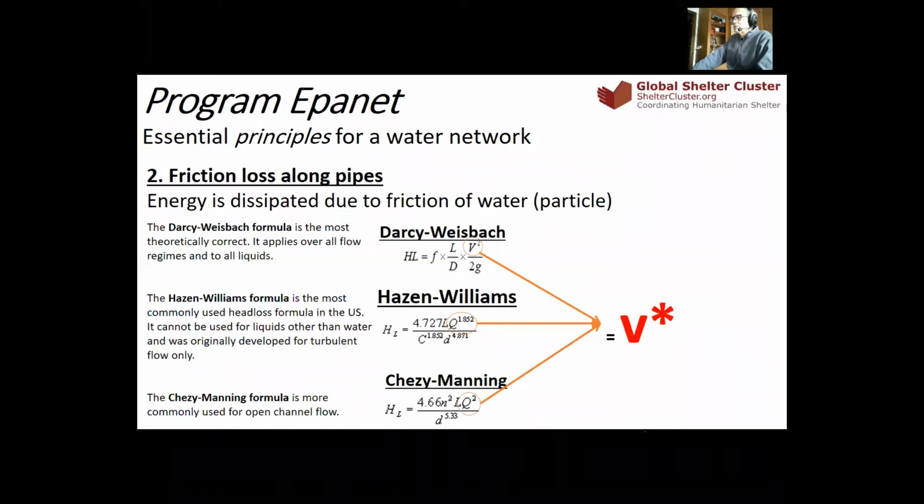I apologize. So if you have a very high tank, let's say on a mountain, it means your water will have a very high amount of energy, potential energy. We are going to speak about that later. So at the tap stand, you are not allowed to have too much energy because you might destroy the pipe, you might destroy the tap, and if not, the water will spit out of the tap too quickly. So you might need to decrease the energy of the water, and one way to do that is to decrease the size of the pipe.